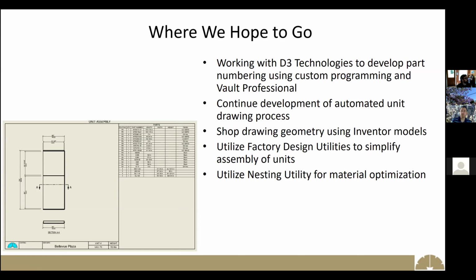But the short answer is, yeah, the STP file is good. It would import back into Inventor in the same look. It imports in the CAM Plus software. They can import the STP file with driver CAD in directly, and then it'll auto recognize a lot of the machinings that they need to use also.